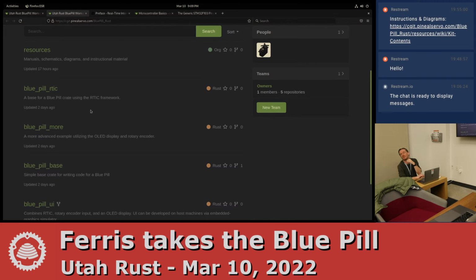So I'll also now pass down LEDs. If you use the black pill, take an RGB, take an ultraviolet, I think it's ultraviolet, and then grab a couple of the colored ones. STM32 F411 or something like that. There's a couple different black pills, but you pick the appropriate model number and then you use the PAL crate that supports that particular model of microcontroller. And most everything else would work the same.